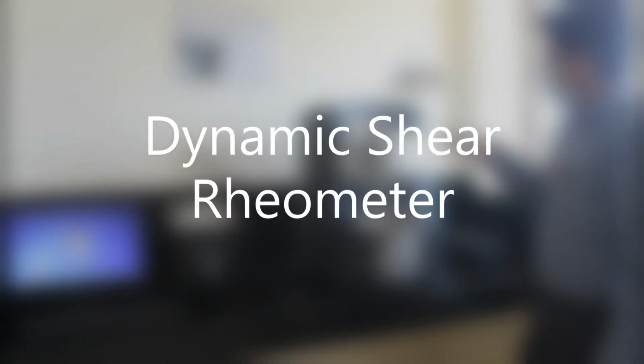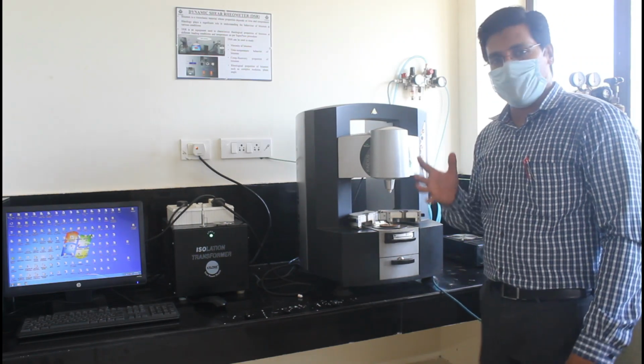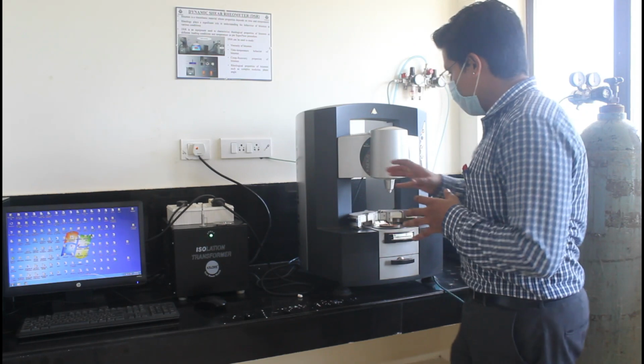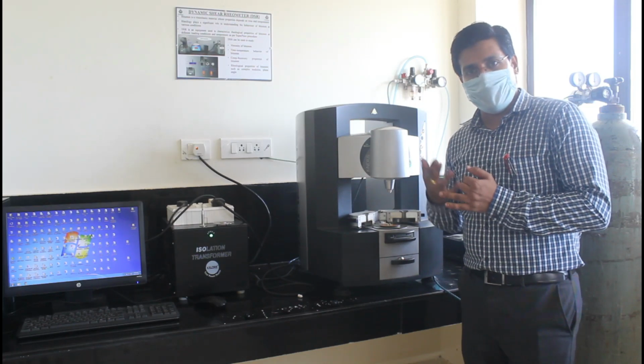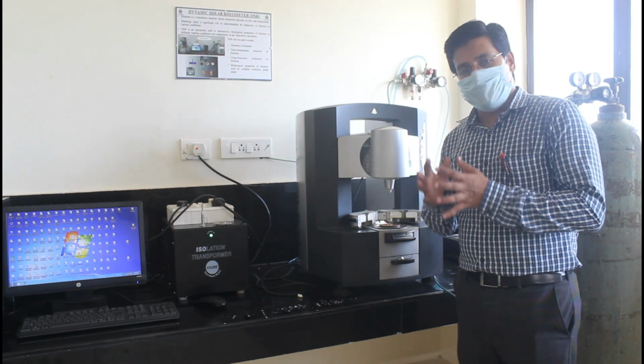Now, this is called a dynamic shear rheometer. As we know, rheology plays a very important role in bitumen characterization. This dynamic shear rheometer will give different kinds of rheological properties. It can be viscosity, complex shear modulus, phase angle, then creep and recovery studies, and stress relaxation